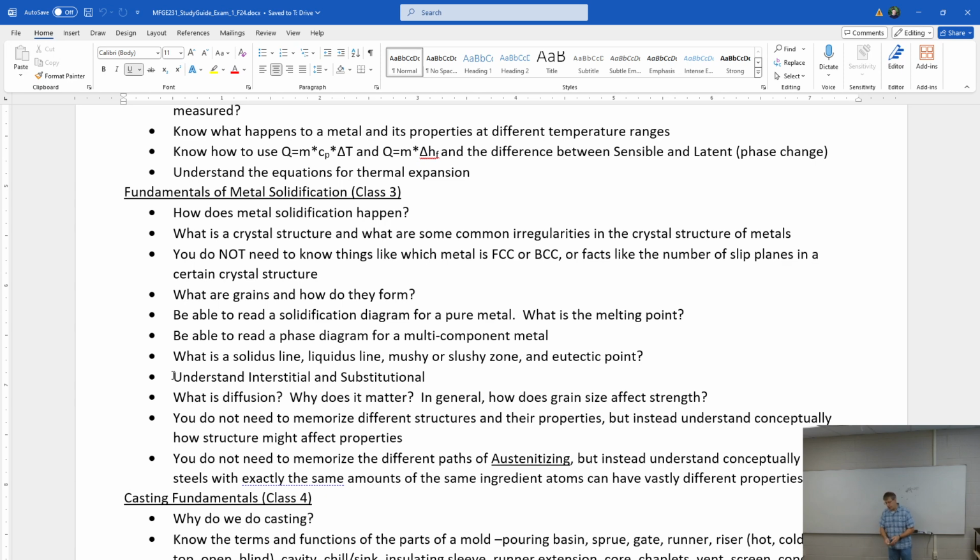So the reason that you quench is because you want to retain the properties that you got. So that is when you are hot working a piece of material. Especially if you are doing impression die forging where you're slamming the thing inside the die. We are forming the grain structure to the shape. And we're also putting in a tremendous amount of strain hardening. But the part is hot, so as fast as it can, it is recrystallizing and getting rid of all that strain hardening that we just put in. And to stop it from doing that so that we can retain the strength, we quench it, which means that we dump it in oil or water or air.